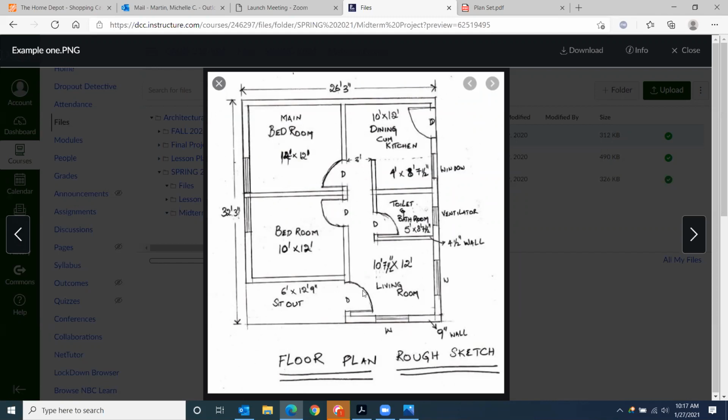But what I want you to do to get an accurate measurement is go from the interior side of the wall to the interior side of the window, to the inside of that sill, then do the window opening itself, so you have the correct measurement of the window. So we'll get the placement of it this way, from the interior of the wall to this side of the window. But when we actually dimension it, there are two different ways that we can do it. So to get an accurate measurement, go interior wall to the inside of the window to the other side of the window. Okay, thank you.